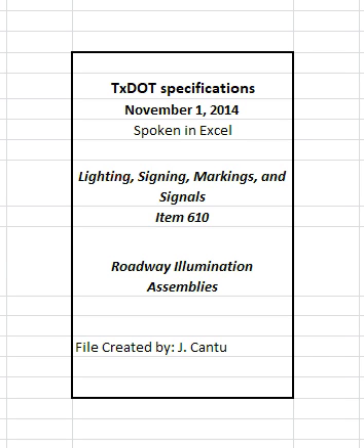3.3 Removal. Remove roadway illumination assembly components in accordance with established industry and utility safety practices. Remove transformer bases from transformer base poles. Destroy removed transformer bases to prevent reuse. Remove luminaires and luminaire arms from the pole shaft. Stockpile pole shafts, luminaire arms, and assembly hardware at a location designated by the department. Pole shafts, luminaire arms, and assembly hardware will remain department property unless otherwise shown on the plans or as directed.